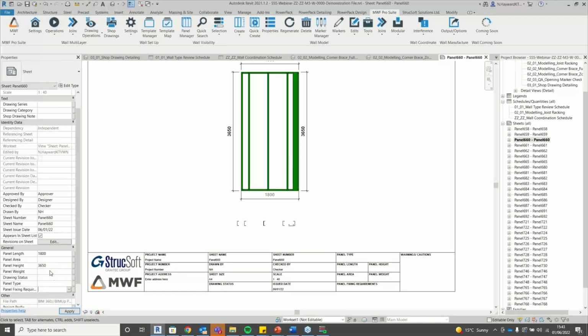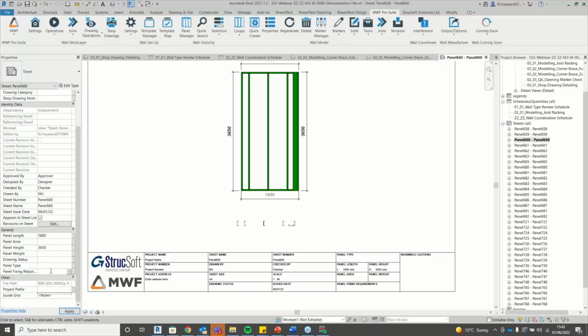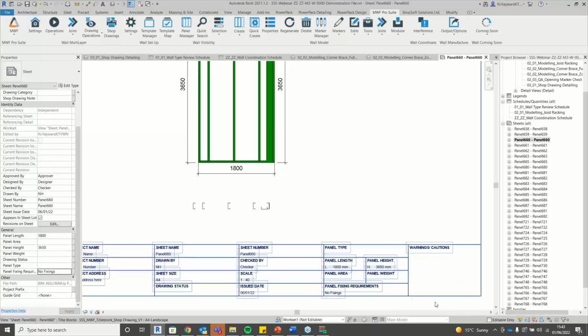And obviously, if we've got a Revit schedule in the background, that could be counting up all the bits of panel data using, let's say, the wall or the individual framing members. So things like the E1 stud or the bottom track stud. We could use those to pull out the top and bottom heights and lengths. Things like the weight, we'd probably have to calculate a little bit with the Revit schedule, but the idea is that a lot of that information is obtainable through a project schedule.